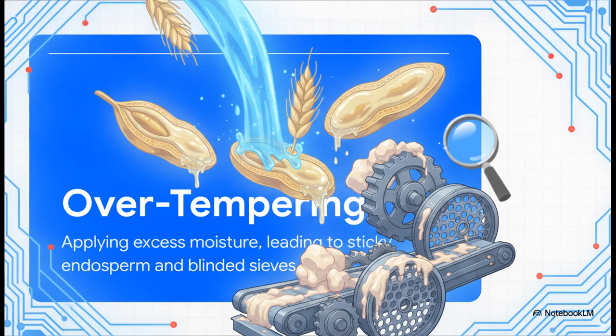The wet starch adheres to the fine micrometer meshes of the plan sifter, a condition we call blinding the sieves. When these microscopic apertures are blocked, material stops grading entirely. Sieve blinding effectively closes off the plan sifter flow, creates an immediate operational bottleneck, and forces a dead halt of the reduction line. Moisture is your primary tool, but over-application is a systemic contaminant.